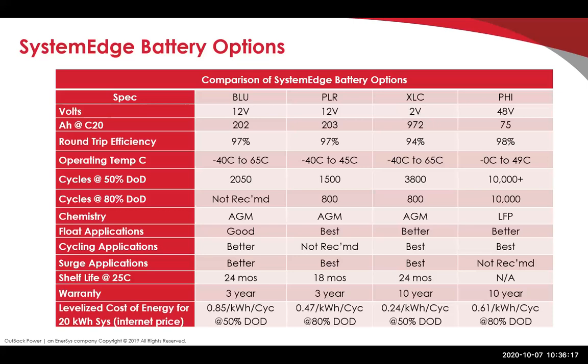If you overcharge them long enough in a hot enough environment, you can get thermal runaway on a lead acid battery. It's not very common, but it can happen, especially with AGM batteries. I don't think it happens very often. I think where a lot of battery fires have started with lead acid batteries is the flooded batteries, because they off gas hydrogen, which is much more volatile. So yes, in general, AGM batteries have a lower threshold of thermal runaway than lithium ion batteries.